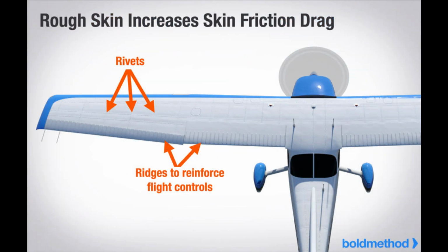Skin friction drag is the aerodynamic resistance due to the contact of moving air with the surface of an aircraft. Every surface, no matter how apparently smooth, has a rough, ragged surface when viewed under a microscope. The air molecules, which come in direct contact with the surface of the wing, are virtually motionless. Each layer of molecules above the surface moves slightly faster until the molecules are moving at the velocity of the air moving around the aircraft.